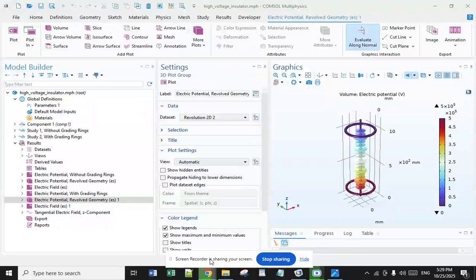When selecting support insulators, it is important to consider the stress level of the system, environmental conditions such as contamination and humidity, and expected mechanical loads, choosing the right material, porcelain, glass, or composites. And the right design is crucial to meet performance and durability requirements. Supporting insulators play a vital role in the safety and efficiency of distribution networks and electrical substations.